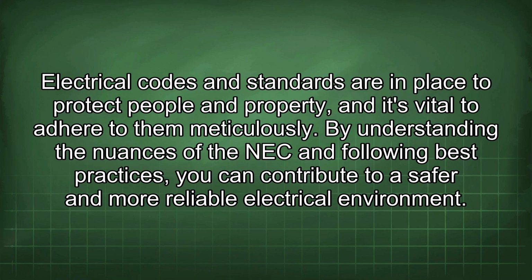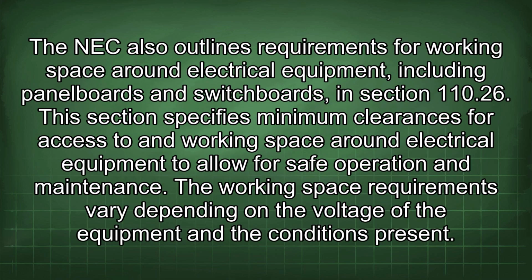By understanding the nuances of the NEC and following best practices, you can contribute to a safer and more reliable electrical environment. The NEC also outlines requirements for working space around electrical equipment, including panel boards and switchboards, in section 110.26.